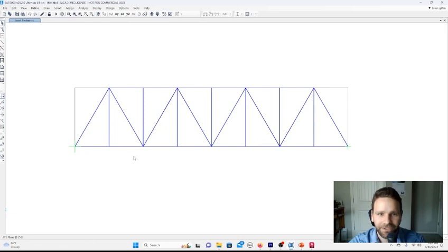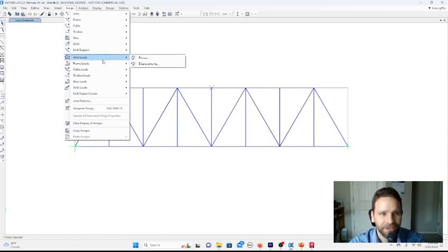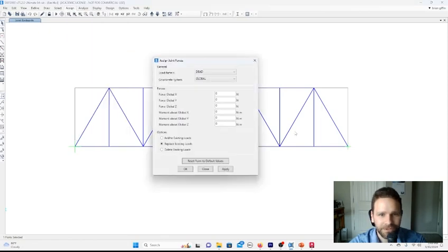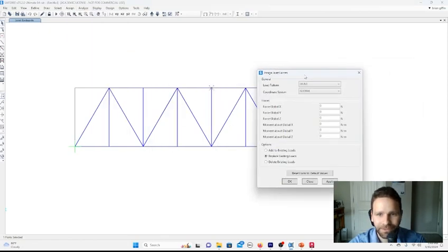The process of actually assigning loads involves either specifying point loads or distributed loads along members. To do that, let's consider applying a point load at this top joint here. Select this point and then go to Assign, Joint Loads, Forces. You can also assign joint displacements as well. Then you can select the particular pattern to which you want this assigned load to show up.